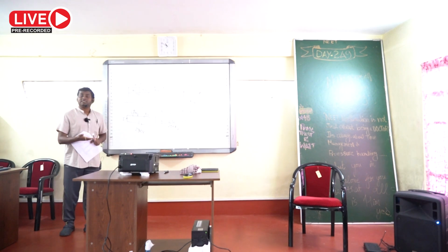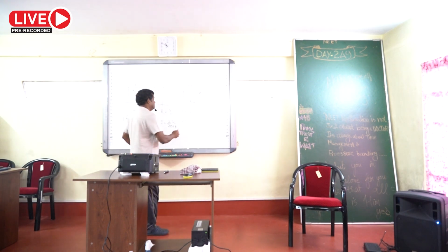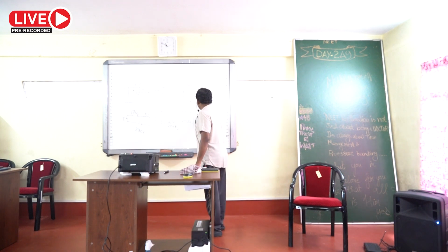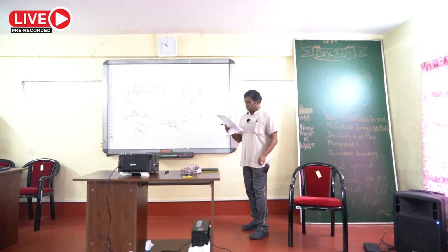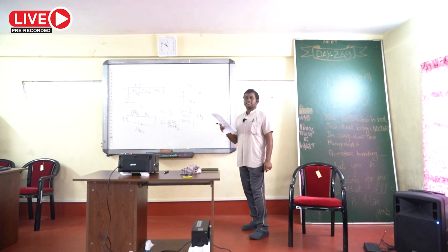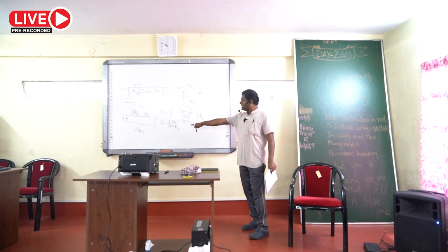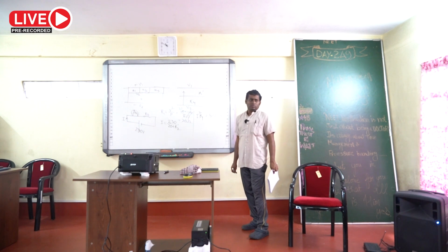Then how much power is developed across R1? That is I square R1, and that is given 500 watt. Because it is mentioned that when this resistance is connected, the bulb consumes exactly 500 watt. Then put the value of I and solve for R2, because R1 is known, only R2 will be unknown in that case.